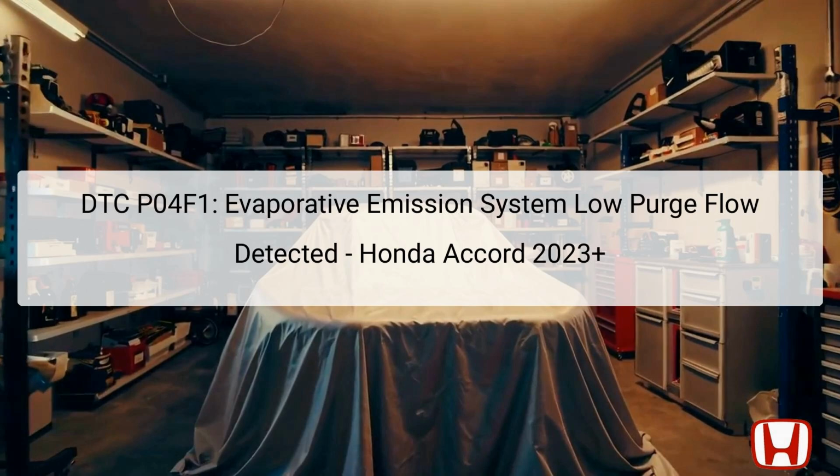All of these parts play crucial roles in minimizing emissions by allowing the engine to recirculate evaporated fuel vapor back into the intake air system. Locations of these components are scattered throughout the vehicle. The EVAP canister is generally located under the vehicle near the fuel tank, while the FTP sensor can often be found near or integrated with the fuel pump assembly. Identifying the issue addressed by this DTC is essential for maintaining emissions compliance and optimal engine performance.